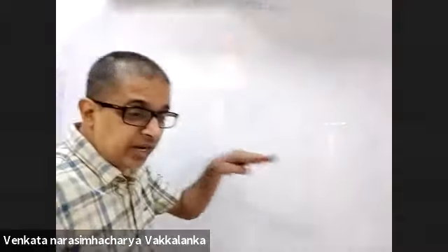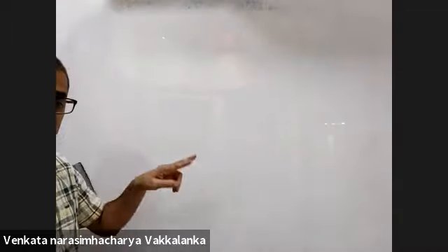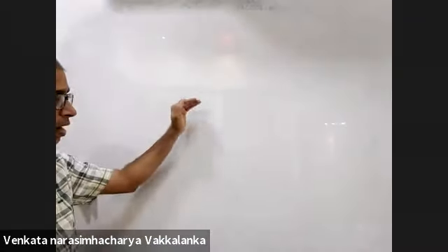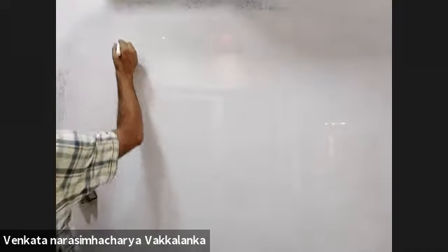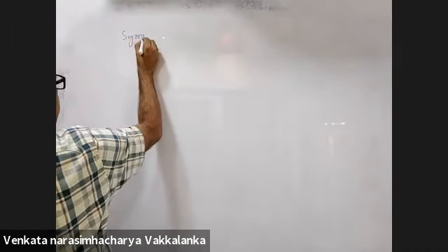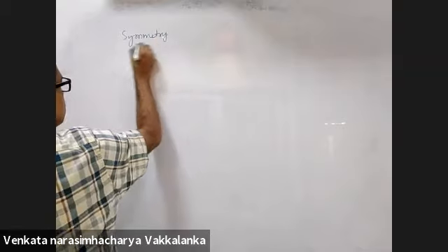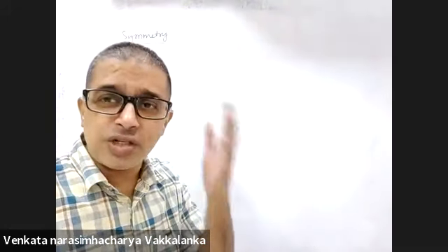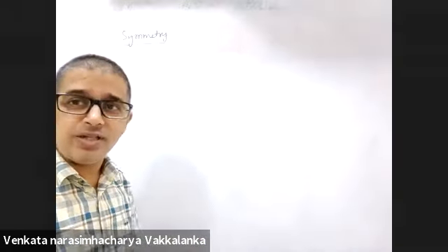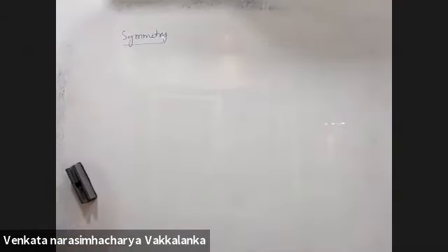Now this is the second stage of the analysis. First was series parallel. If I cannot see series parallel, I'll search for a Wheatstone bridge. What if Wheatstone bridge is also not visible? Then search for symmetry conditions. Symmetry is something that should strike to you at that particular instant. It is not a standard rule. You can look at it in so many ways.